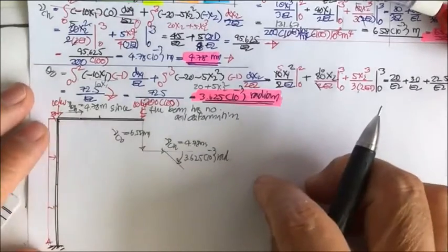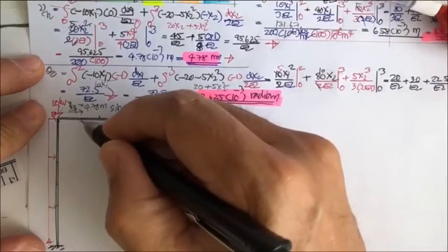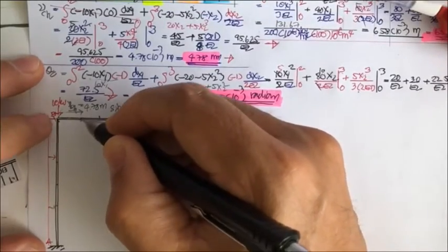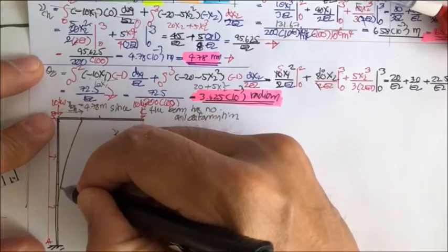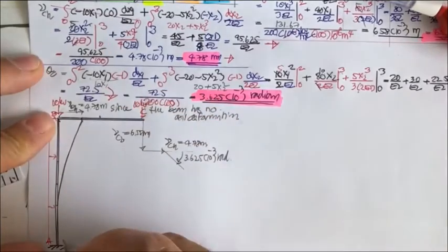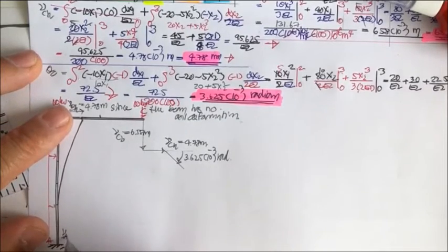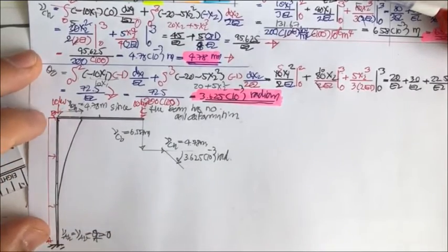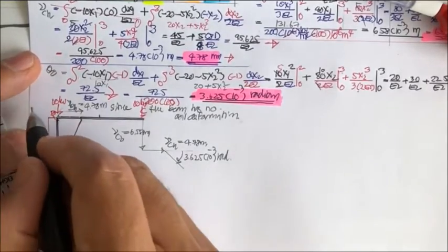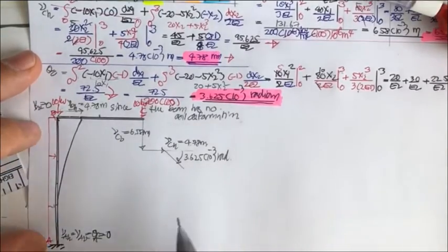This one moves, so when you put this like here, it's going to arrive here, that is going to be B prime, so it's going to have the deflection like this. As you may know, V sub A H, V sub A V, and theta sub A are all 0. And over here, you also have V sub B V equal to 0, if you like to check.